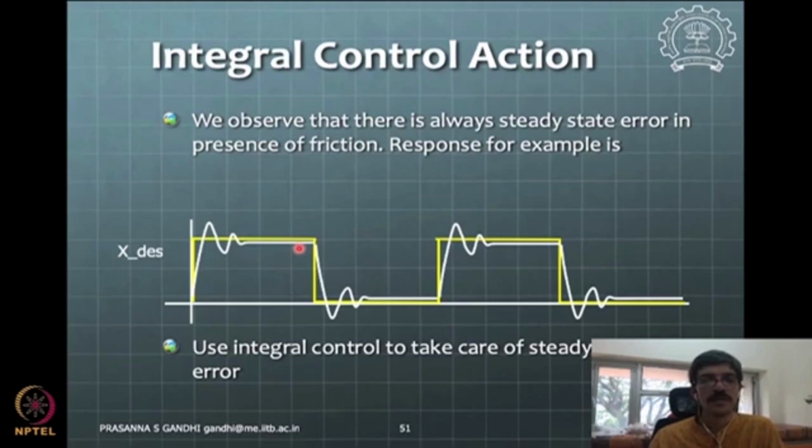By considering your friction model, or there are many other techniques also available. You use this friction model and something called the describing function method to find the frequency at which your system will keep hunting.